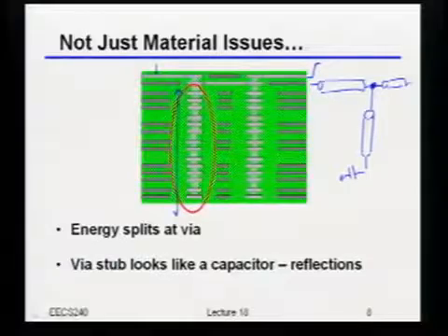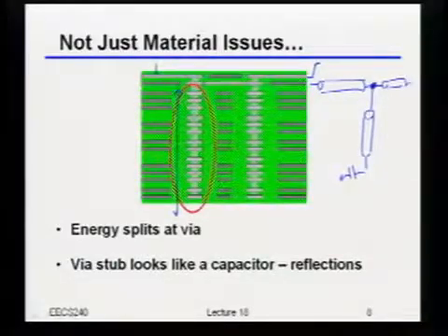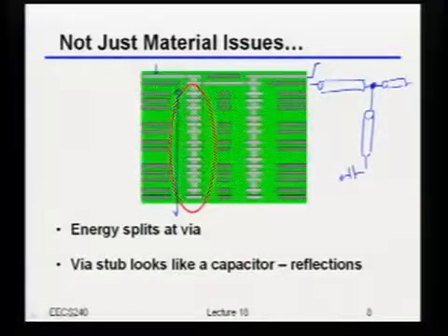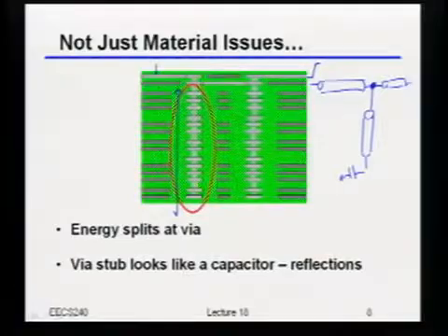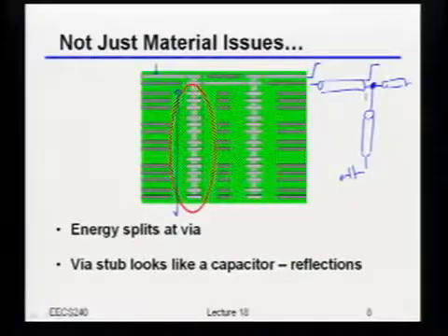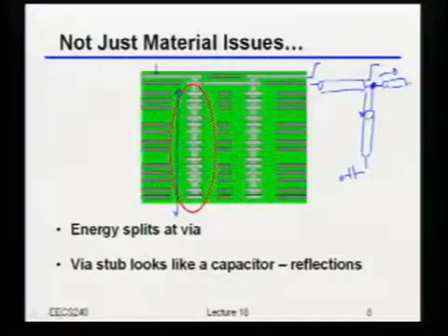Just from a very simple standpoint, like zero order. Fill the via capacitance. Yeah, so basically the step is going to try and show up over here, and some part of the step is going to go that way. Some part of the step is going to go that way, right?